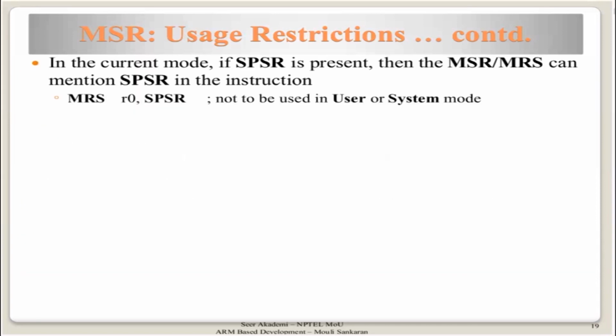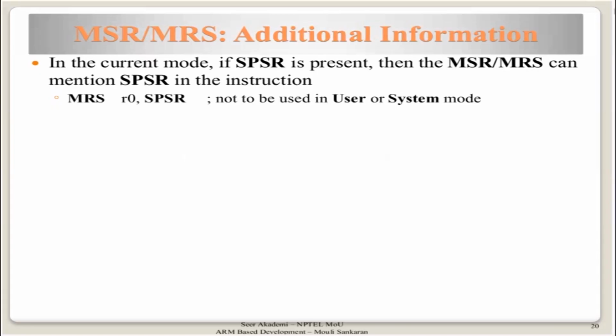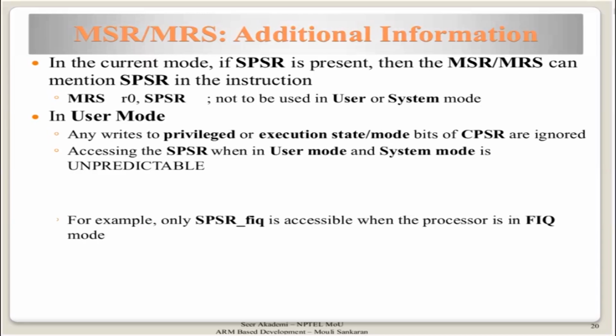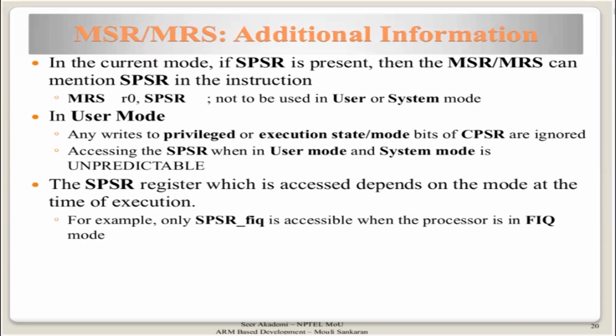Additional information: you can do any operation with SPSR only when that particular mode supports it. You cannot do it in user mode or a system mode which doesn't have an SPSR register. Similarly, only in privileged modes can you modify the SPSR. Also, the SPSR register which is accessed depends on the mode at the time of execution.